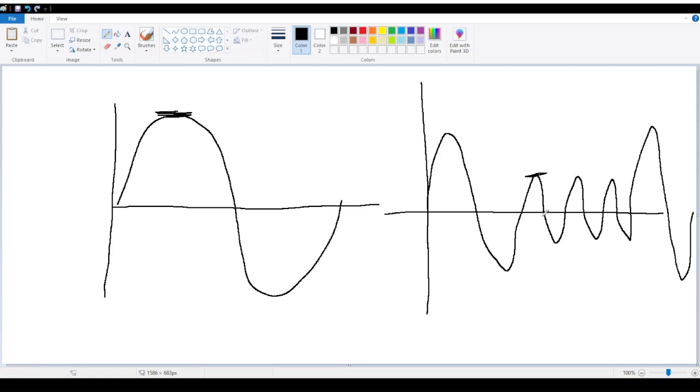So we're going to be doing that every 10 milliseconds. And the reason we're doing it every 10 milliseconds, actually in the code, I should do this in another color. In the code, once we sense this value, we sort of rectify it in the code. Right, so we'll change it to that. So everything is like that. So basically what that means is, instead of doing this every 20 milliseconds, like waiting, let's go back to black, instead of waiting to get to this point every time before we start trying to sense the peak, we can just do the reset every 10 milliseconds.